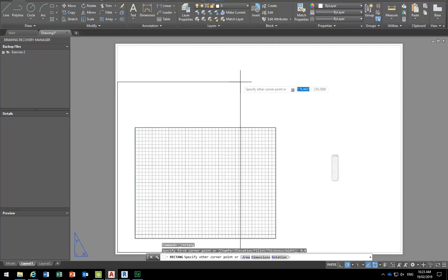A4, is 210 by 297, and then double 210 is 420, of course. So 420 by 297 is A3. And then to get to A2, you double the shorter side again. So 297 times 2 is 594. And 594 by 420 is A2. Going up to A1, you've got to watch out though, because when you go to A1, double A2, 420 is 840, but you add 1 millimetre when you get to A1.